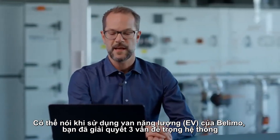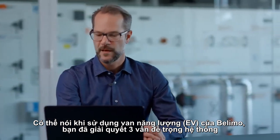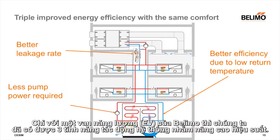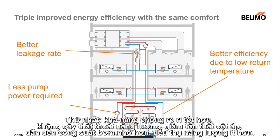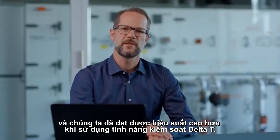In summary, it can be said that with the Belimo energy valve, you can achieve a triple improvement in energy efficiency with the same comfort. Only with this one valve, it is possible to have an influence at 3 points in a building. A better leakage rate reduces the energy flow, reducing the differential pressure leads to less pump power, and we achieve higher efficiency at the boiler through delta T management.